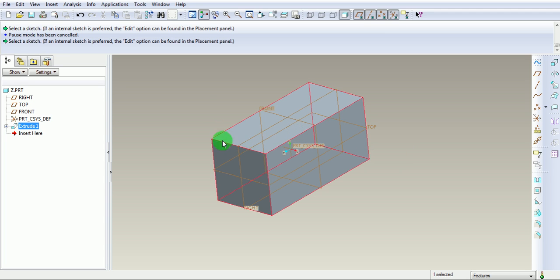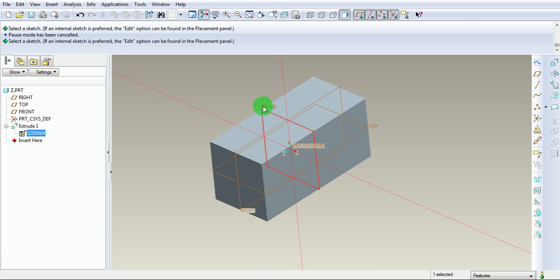To make this extrude, a sketch was used. This sketch was created using the vertical and horizontal center lines, and the vertices are made symmetric about the vertical axis, and these vertices are made symmetrical about the horizontal axis.